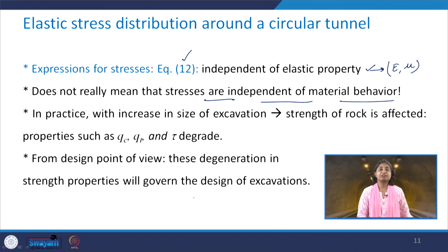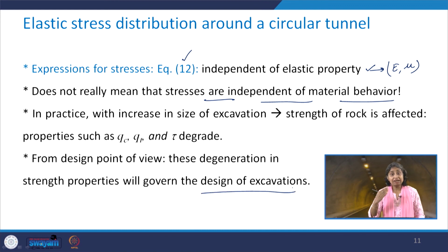What happens in practice is that when you increase the size of the excavation, the strength of the rock is influenced, and the mechanical properties such as its uniaxial compressive strength, tensile strength and shear strength degrade. So, from the design point of view, these degraded values of the strength characteristics govern the design of the excavation. So, indirectly that is how the elastic properties come into the picture.